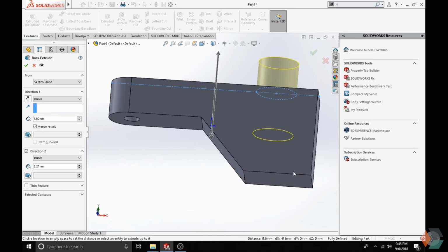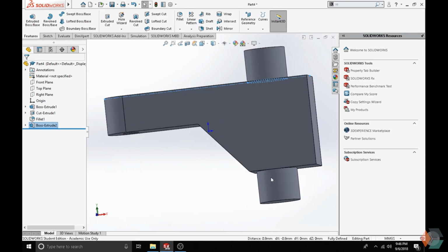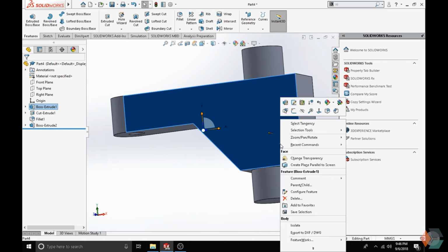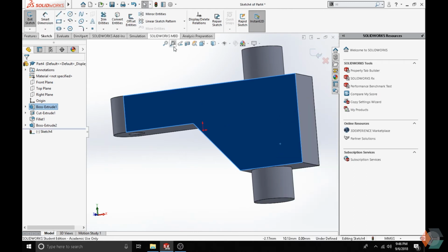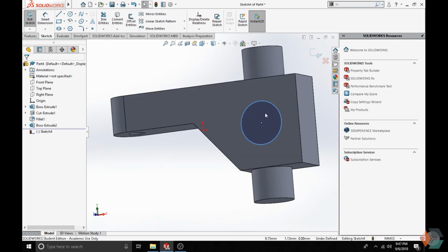of this object. So for the other opposite direction of extrusion, let's change that to be 3.82 millimeter plus 10.77 millimeter, just like that. Next, we can create the ring on this plate. Right click on it, select sketch, hit the S key, and select the circle creation tool. Draw a circle on it, and then exit out the tool.